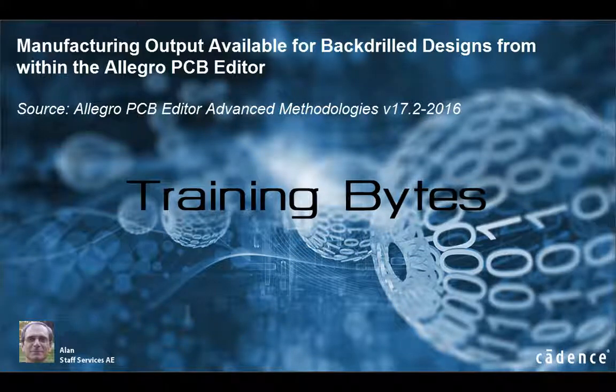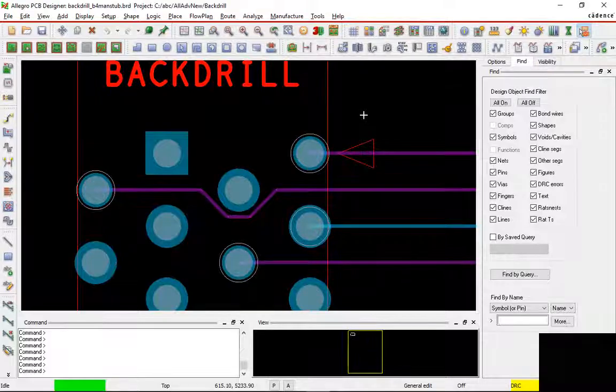This video will demonstrate the manufacturing output available for Backdrilled Designs from within the Allegro PCB Editor. This will include backdrill data available for viewing, DRC and shape voiding, NC drill legend for backdrills, and the backdrill cross-section chart. First, let's view the backdrill data available in the design canvas.